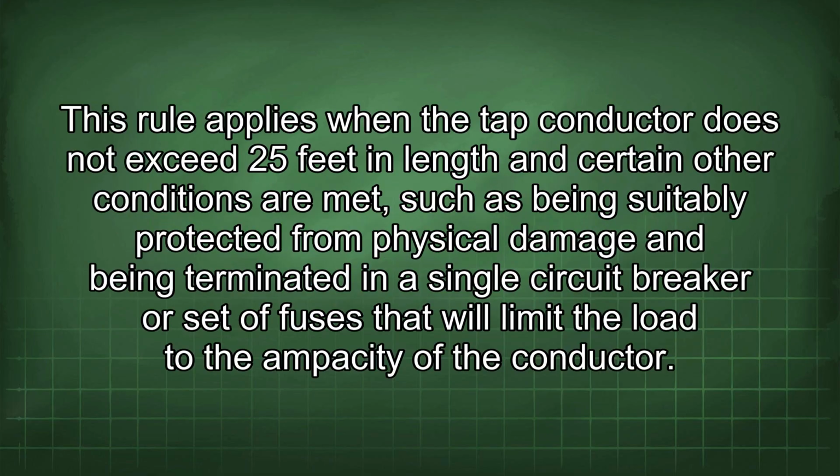This rule applies when the tap conductor does not exceed 25 feet in length and certain other conditions are met, such as being suitably protected from physical damage and being terminated in a single circuit breaker or set of fuses that will limit the load to the ampacity of the conductor.